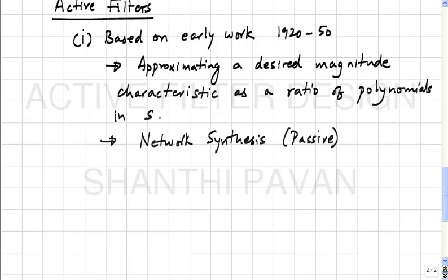So in principle, though we don't know how to do it just yet, it seems that using active elements, R and C, one must be able to put poles anywhere, which means that you can get arbitrarily sharp filters, okay, using only transistors, resistors and capacitors. And commercially this is extremely important, because transistors are very, very tiny, okay.